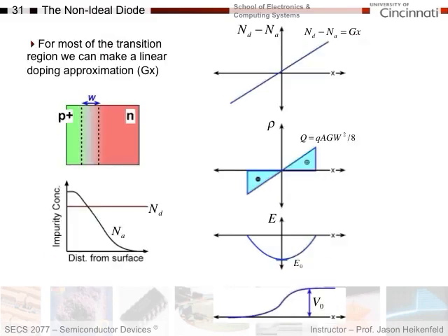Well, if you look at your concentration profiles, this is concentration versus distance from the surface, okay, for the boron and the phosphorus. Now remember, the phosphorus was what I mixed in with the silicon when I made that big rod. So it's evenly distributed in concentration throughout the whole wafer.